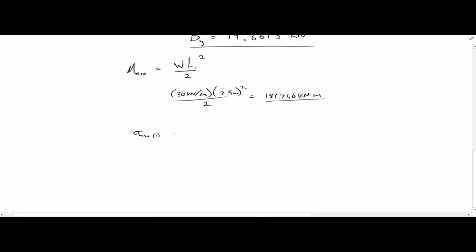And so now the bending stress in the steel beam without the assist from the timber beam is going to be this moment, 183.750 kilonewton meters, multiplied to our 200 millimeters, so the half of the depth of the steel beam. Now we have a unit conversion issue, and then divide by the moment of inertia, which is a given, times 10 to the 6 millimeters to the 4th. And so then we'll multiply this by 1,000 millimeters per 1 meter, divide all this out, and you should get 282.692 megapascals. And then this is the solution for part C.